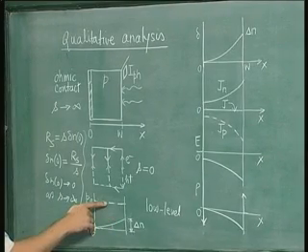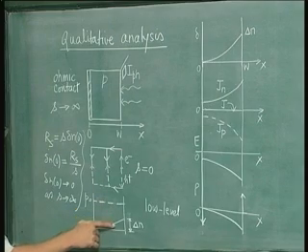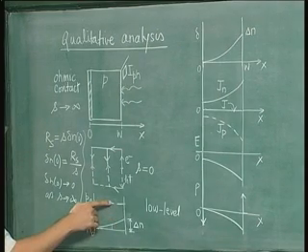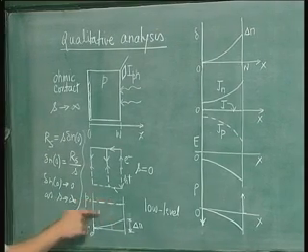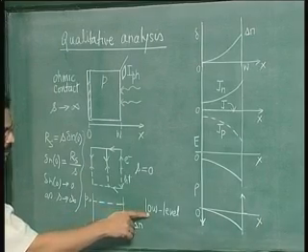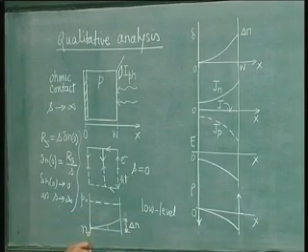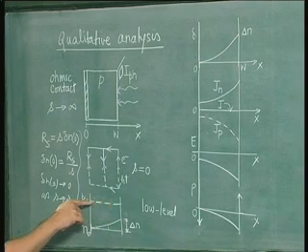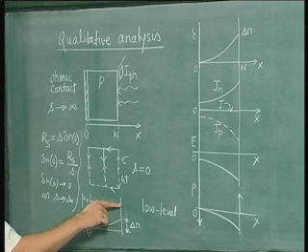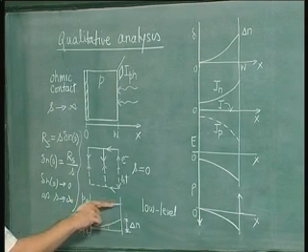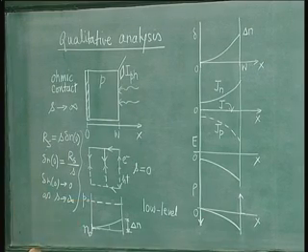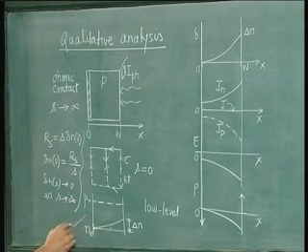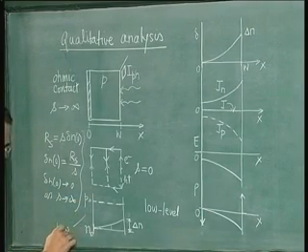I emphasize that delta n is equal to delta p, so you also have excess holes, but on a log scale under low injection level, as we have discussed earlier, there will not be any disturbance seen. So you are not able to see that delta p here. It almost appears to be constant, equal to the equilibrium value on a log scale.